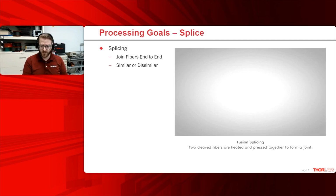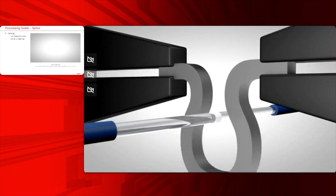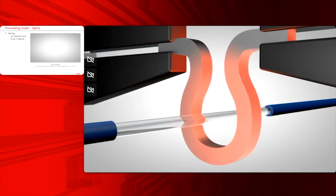So what do I mean by splicing? Splicing is the process by which you join two fibers end to end. So typically what that entails is bringing the fibers together, applying some heat, and then moving one into the other so that the glass flows and a joint is formed.